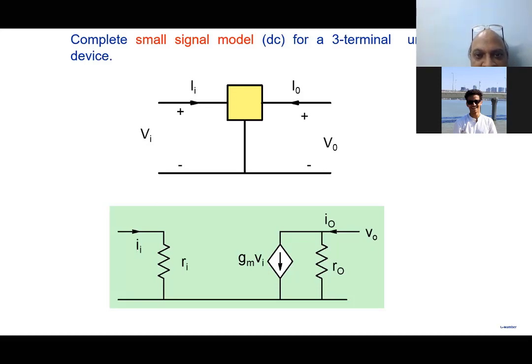So when we have an amplifier circuit, in general, you will find that you will have DC voltages and currents that are there. And then the quantity of real interest for us is the small signal that we introduce into the amplifier, the audio signal or video signal that we want to be amplified. And therefore, when we analyze amplifier circuits, we need to do a small signal analysis of our amplifier circuit. And therefore, small signal models of the elements are important.